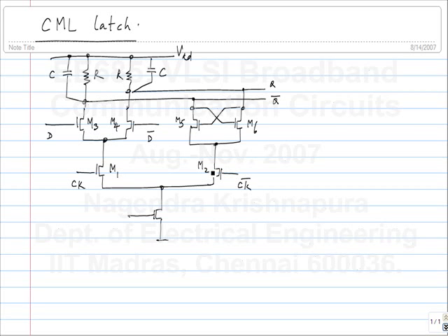Okay. So, someone give me the definition of setup time and hold time. Maybe I have it backwards. So, let's say the data input is here. The clock does this. I have clock here. So this is the sample phase. Sample meaning detect the input, and this is the hold phase. Now, the idea is that the data can change anywhere in this interval, and at the end, during the hold phase, the value at this point during the negative edge of the clock will be held. That's what we want.